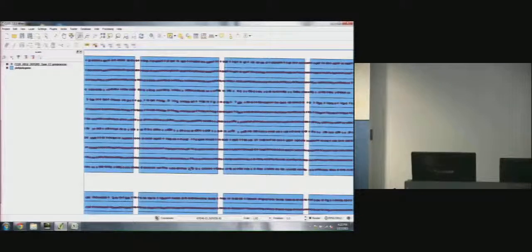So the northing difference between the receiver location and this line of coordinates, and similarly this line of coordinates, would be larger than between these two lines. And so I'm betting that when you do that trigonometric transformation to get those values, the heading errors contribute to more error in the outer points on the boom.